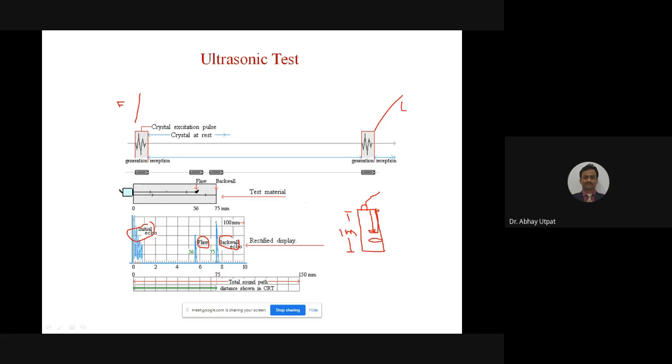So it is shown here. In this figure also you check presence of crack, sound wave reflects back. Now, if this crack is to be tested, sound waves are sent from this side. And then you can check from how much distance. So the advantage of ultrasonic test is it is used for checking subsurface cracks. Subsurface crack means below surface level. But what is the disadvantage? The disadvantage is you can't see the crack.